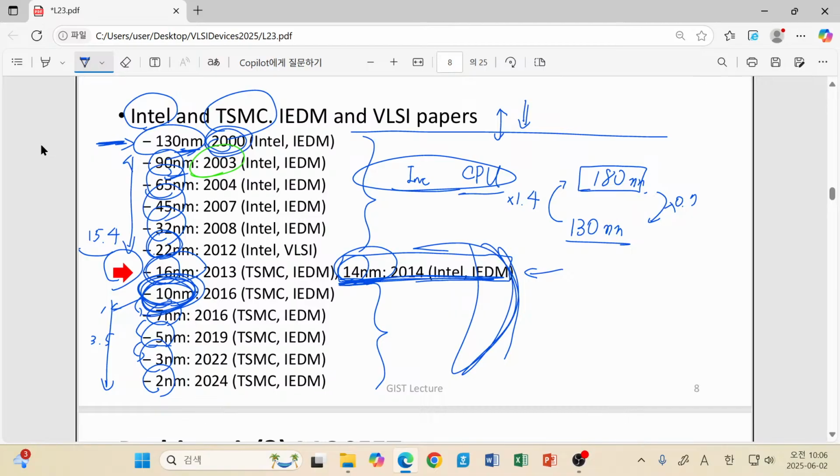So maybe you have now heard about Intel's 18A node. Nowadays there are some buzzwords about this technology. Intel is nowadays talking about, oh, we will make an 18 Angstrom node and soon it will be delivered to the customers. So 18 Angstrom is corresponding to 1.8 nanometer. However, there is no real 1.8 nanometer in that technology. That is regarded as just a naming convention. Every company nowadays uses these numbers just to designate their new technology. Introduce a small number and just name them.